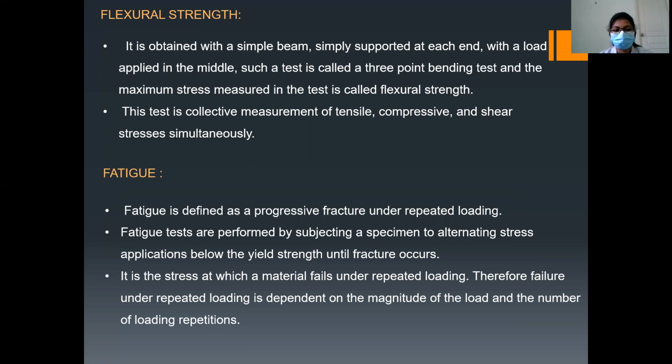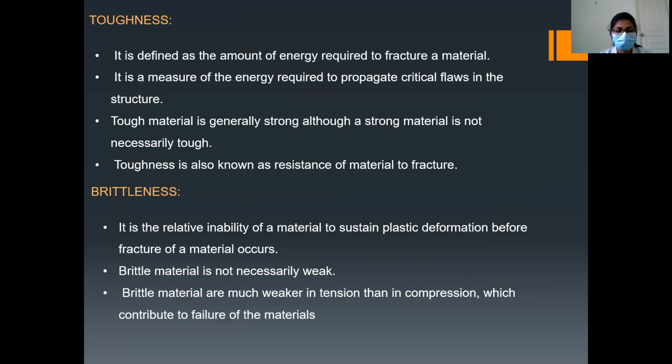Fatigue. Fatigue is defined as a progressive fracture under repeated loading. Fatigue tests are performed by subjecting a specimen to alternating stress applications below the yield strength until fracture occurs. It is the stress at which a material fails under repeated loading. Therefore, failure under repeated loading is dependent on the magnitude of the load and the number of loading repetitions.